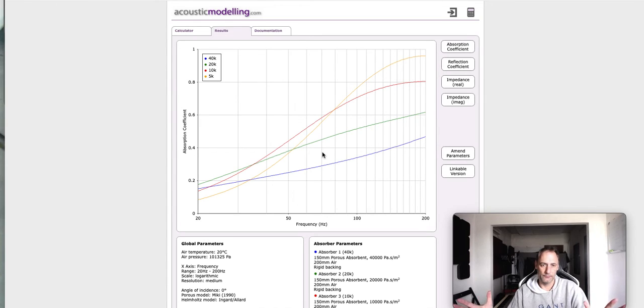So usually my starting point is first the thickness of the material that I can use, which is the maximum thickness that I can use. Is it 5 centimeters, 10 centimeters, 20 centimeters? That's very important. Then I always add an air cavity behind, unless there are huge constraints in terms of spacing.